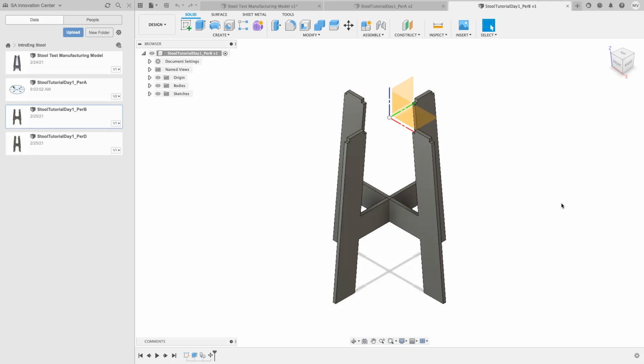All right, okay. So first thing we're going to do, I'm going to create a sketch on one of the faces of my part. Now, this is not always recommended, but it works sometimes. I'm not going to get into the details of when you should use this and when you shouldn't, but suffice it to say, if you sketch on part of your model that's already made, you've got to be really sure that that part is not going to change and it's going to just be there all the time.